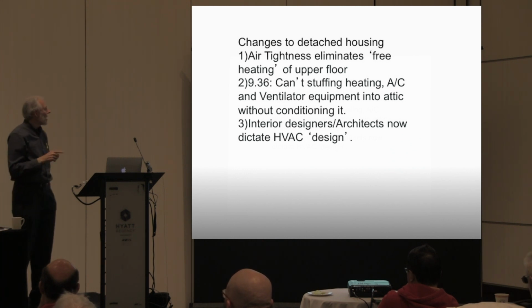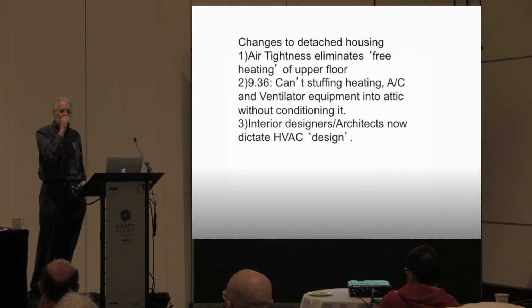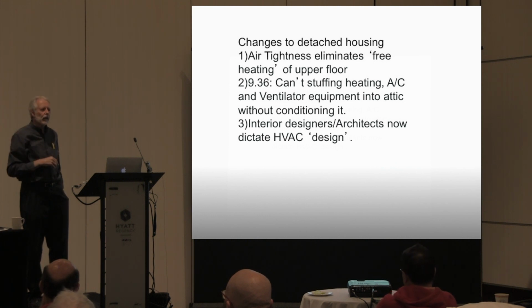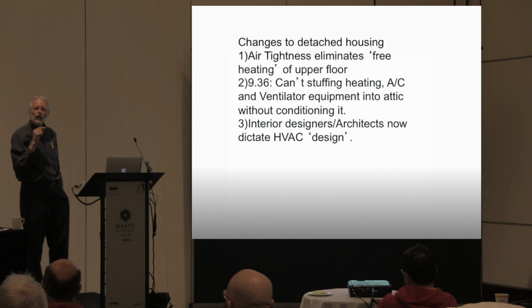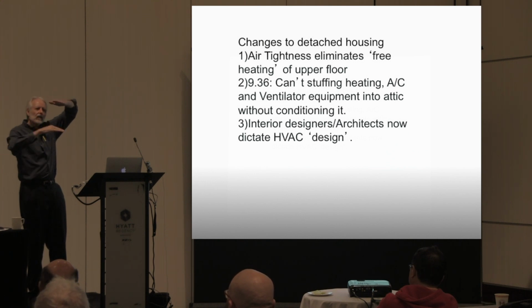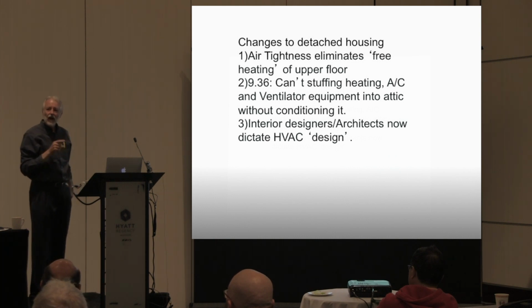That is changing today, and if any of you people built under the R2000 program, have you ever been burned with a top floor that doesn't heat adequately, which is the natural result of building a house that's airtight, because you don't get the heat on the main level giving you a free ride upstairs. Your top floor needs heat just as much as the main. In fact, it's worse than that. I'll get into it.